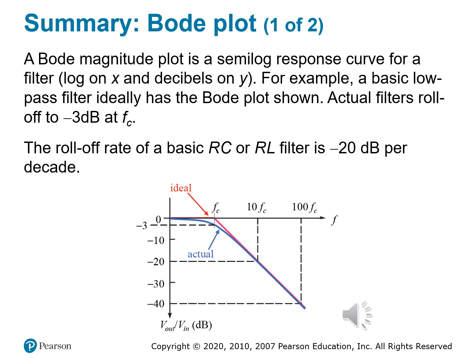So in the example, we have a low pass filter. It rolls off at the critical frequency f sub c. And again, remember, that's where the gain drops to negative 3 dB. After that, the filter begins to attenuate more rapidly.